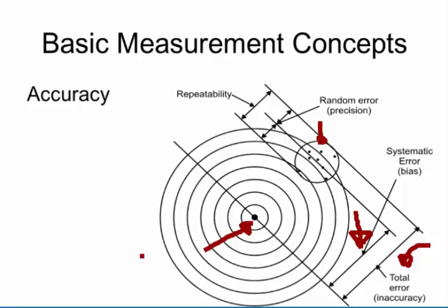Okay, the one with greater repeatability, I should say, the one with less spread of repeatability. So you are making the readings tighter together. Then what you do is you can put a bias in there. In other words, you're bringing the total error towards the real error.